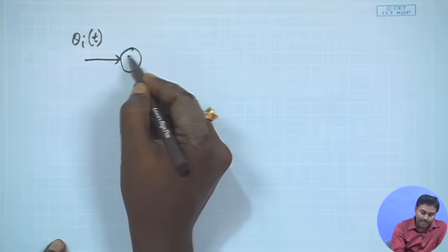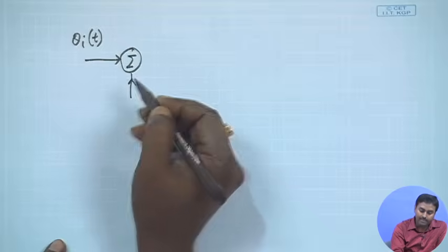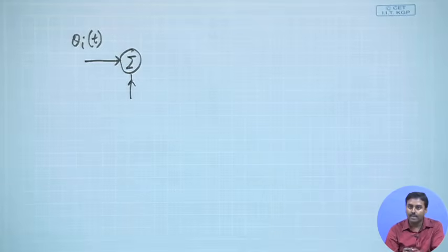It is just this phase which will be tracked and controlled, so this phase has to be properly designed. This is the phase which is coming in, and then after that I can put an adder circuit. This is where the multiplier becomes an adder, because from the phase terminology it is just phase addition or subtraction.